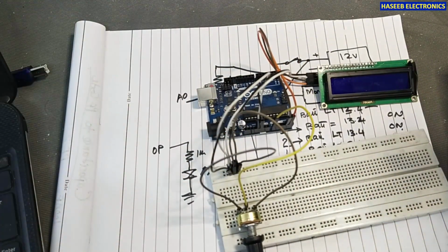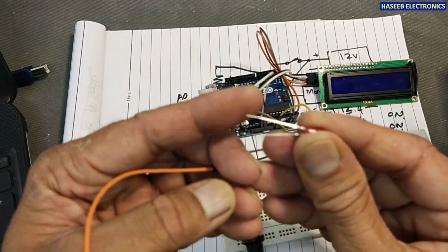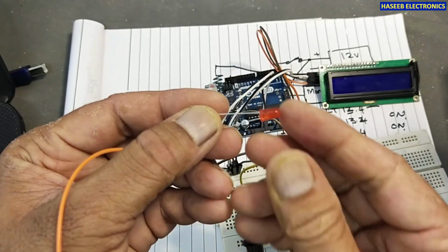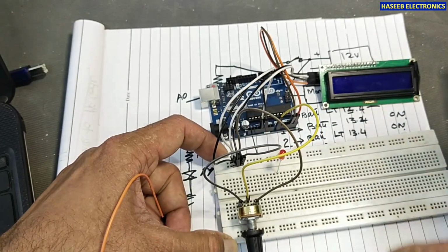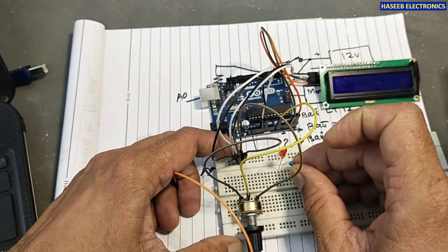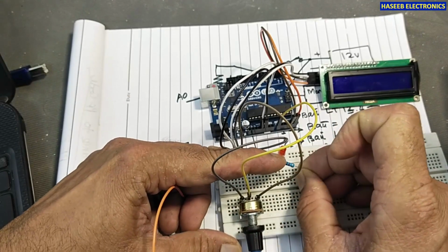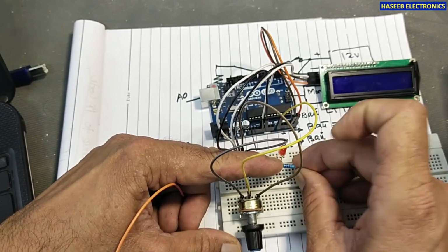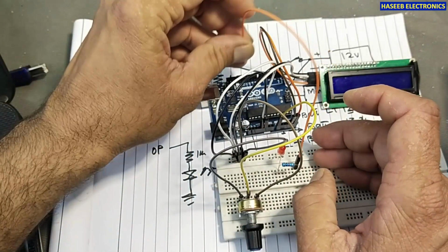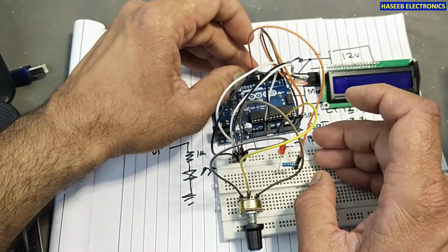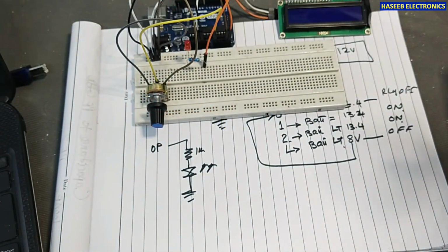I connected it here, and we will take the output from this board and connect this LED's small pin to the ground, so that it will indicate the signal, and we will connect a 1 kilo ohm resistor. It is better to use 1 kilo ohm, so the light will dim, but it is safe. We can connect to any pin. Okay, I am connecting to pin number 9, no problem. So our setup is now ready.